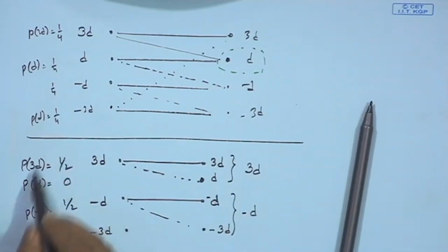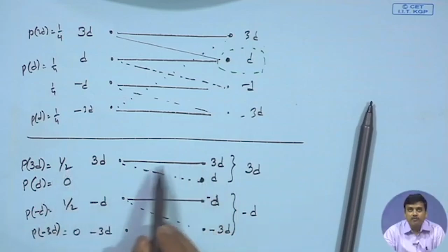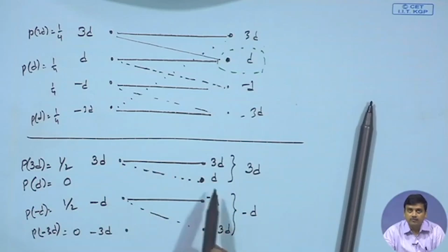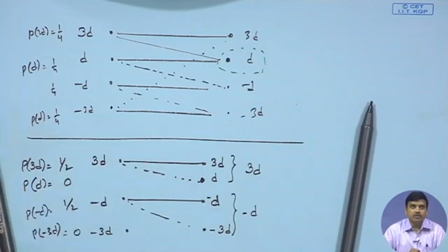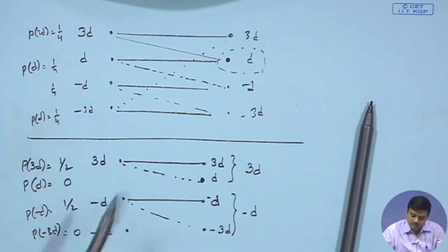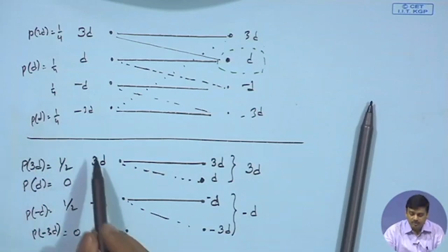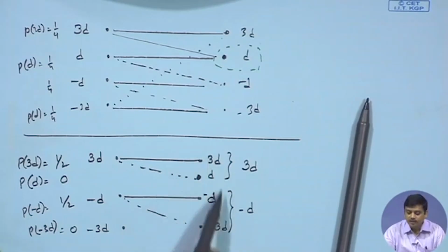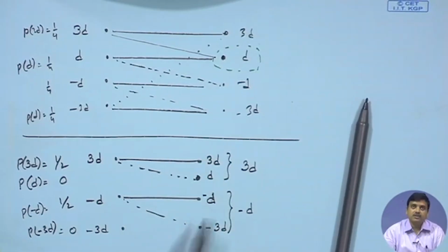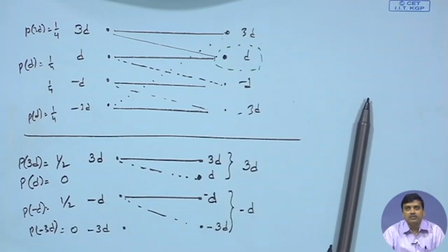So, by assigning these probabilities, you avoid any confusion and you would maximize the mutual information. That means you would like to maximize the mutual information over all possible source probabilities. You could choose any other combination, but if we choose this as one of the combinations, we avoid any kind of confusion at the receiver. So, this is all that it means. In other words, you can say that it makes the probability of making an error almost 0.